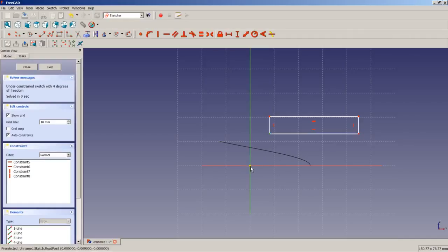As I have said before, with FreeCAD, it is better to have overlapping solids when doing a Boolean operation, because we want to fuse all the blades to the cylinder in the end to get one solid.